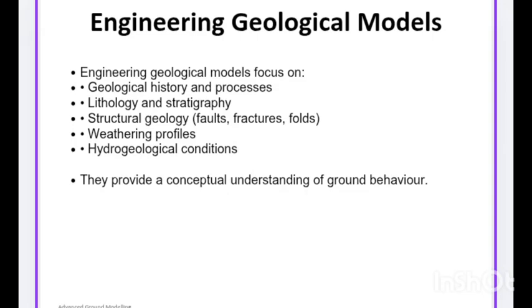Number four is hydrogeological conditions. Groundwater strongly affects slope stability, soil strength, excavation conditions, and seepage. And we have the geological processes. Processes such as erosion, sedimentation, and tectonic activity influence subsurface conditions. So engineering geological models are generally conceptual and descriptive. They form the foundation upon which geotechnical analysis is built.